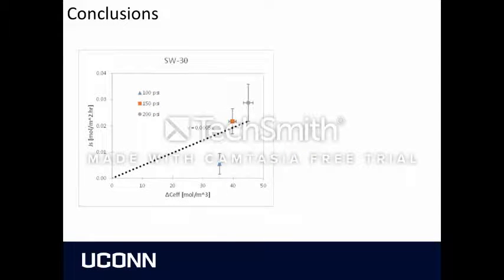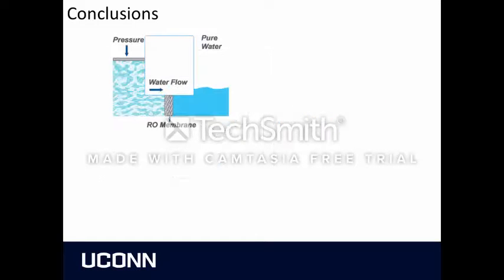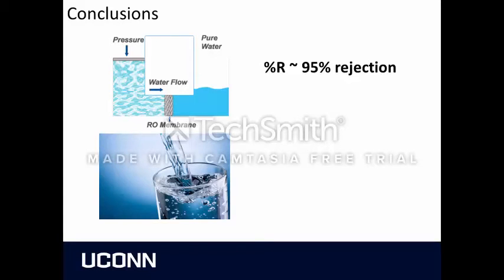Some of the linear trend lines do not match well with the data. If we were to avoid manually setting the y-intercept at 0, the slope of this linear trend line more closely matches the theoretical value for the solute permeability constant. Overall, our goal was to prove the effectiveness of osmosis systems in the purification of salt water. Although we achieve very high percent salt rejections, these technologies still need to be developed before they can produce viable drinking water and be implemented on a larger scale.